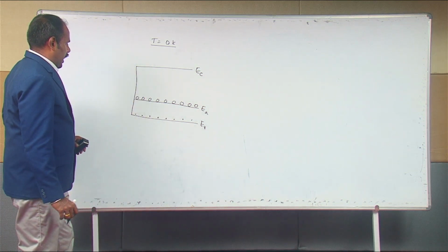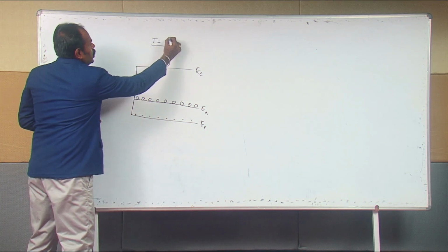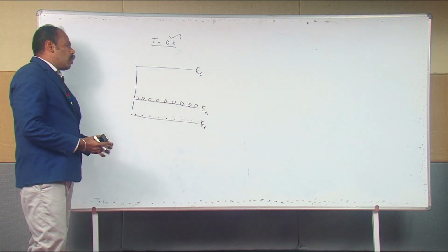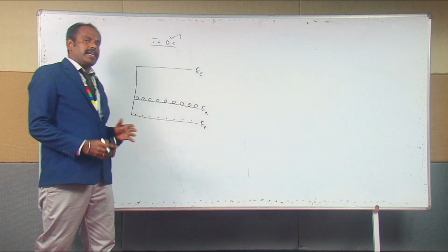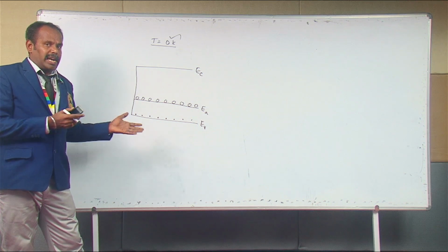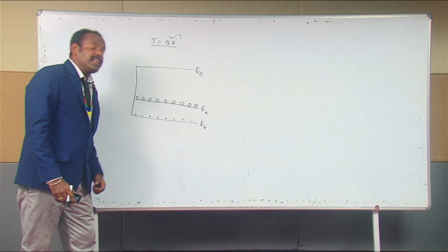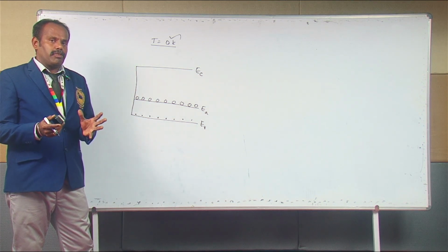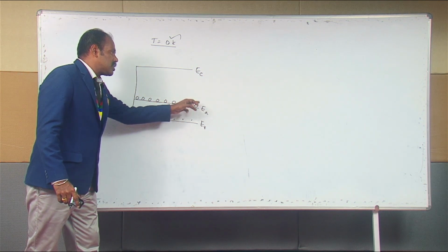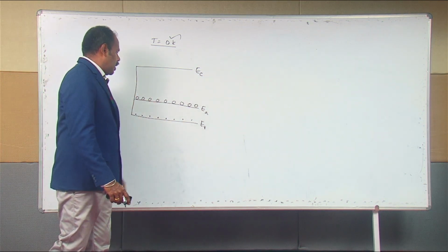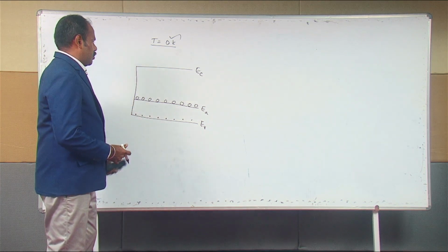Okay, right. Now when T is equal to 0 Kelvin, this is the scenario. You won't find the presence of any electron in the conduction band, and thereby the material is not behaving in its conducting state. While you also have the presence of valence electrons in the valence band, completely encased in the formation of covalent bonds, and you also have the presence of acceptor sites at the acceptor energy level because of the addition of the trivalent impurity atom.